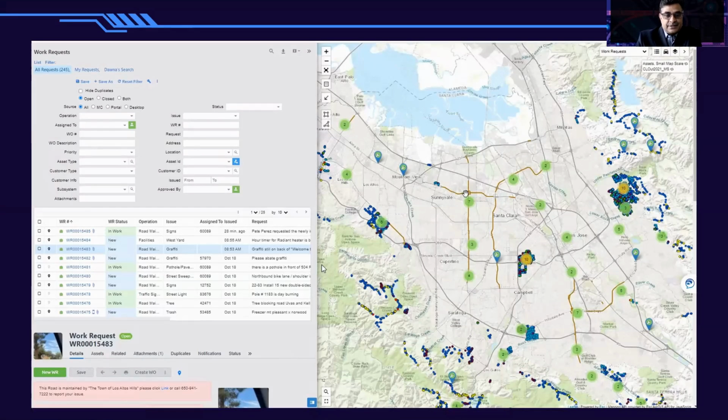And like I said, some requests take time. If somebody requests a stop sign through the system, it may take 3 to 6 months because we have to collect new data as part of the process. A traffic engineering study has to occur to see if this stop sign is warranted based on the current traffic conditions. And if so, it has to go to our Board of Supervisors for approval of the stop sign installation. That itself will take about 2 months. So things can take some time, but most of the issues that you submit will be handled within a day or two.